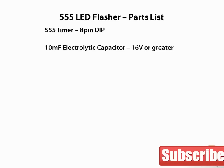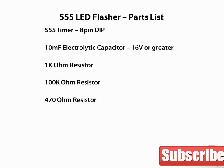The parts that we're going to need for our 555 LED flasher circuit are as follows. We'll need a 555 timer, and since we're using a breadboard, we'll want the package variety of an 8-pin DIP, which stands for dual inline package. We'll need a 10 microfarad electrolytic capacitor, 16 volts or greater. We'll need a 1K ohm resistor, a 100K ohm resistor, and a 470 ohm resistor.